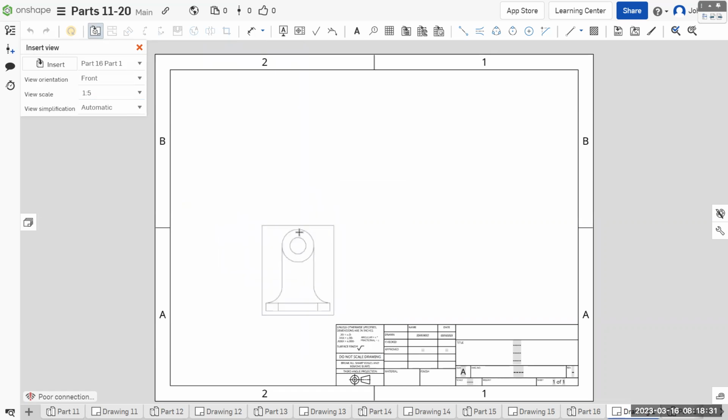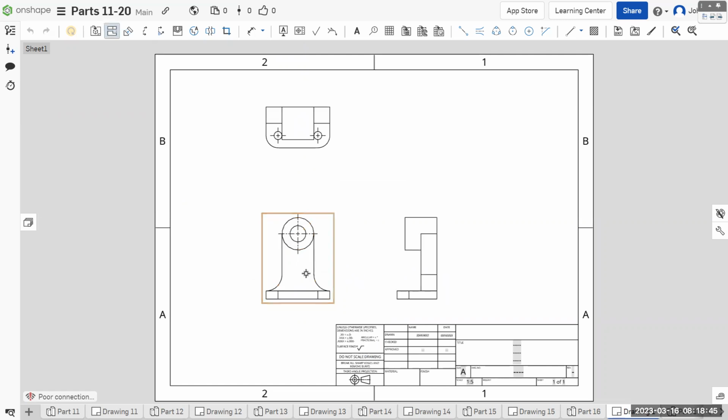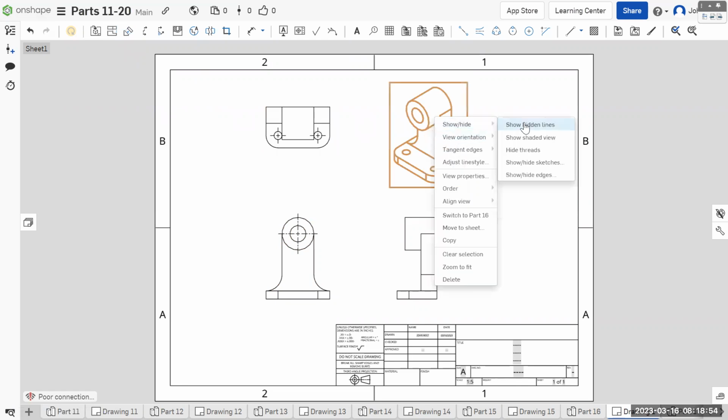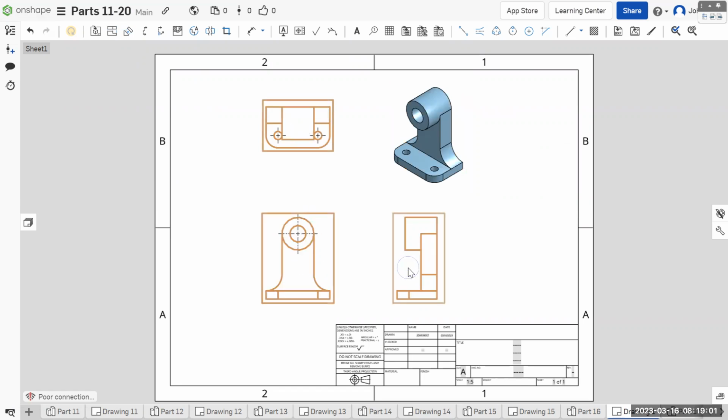It is a larger vertical aspect ratio part on our sheet. That's always going to be horizontal, so I'm not surprised it's a smaller scale, 1 to 5 compared to our 1 to 4 or 1 to 3 situation as usual. Okay, cancel the project view. Right click, show shaded view, and hold down shift, click them all. Right click, show hidden lines.